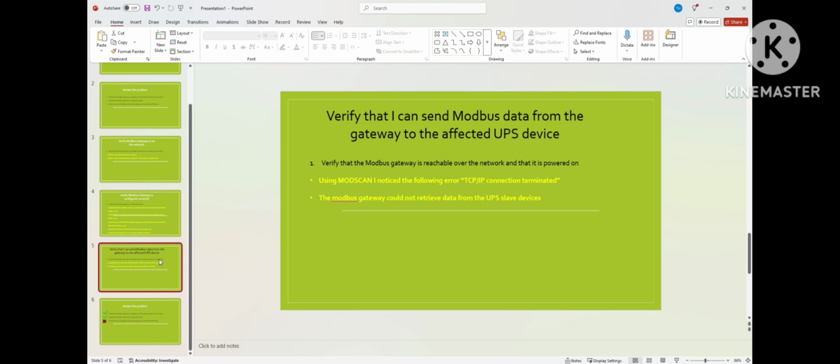Basically how you use it is you plug in, in this case, the Modbus gateway IP, and we select service port 502, because that's the default Modbus protocol port it uses to communicate. And then we pick a slave address. In this case, let's say we wanted to talk to slave 1, since that's the first one in the chain.